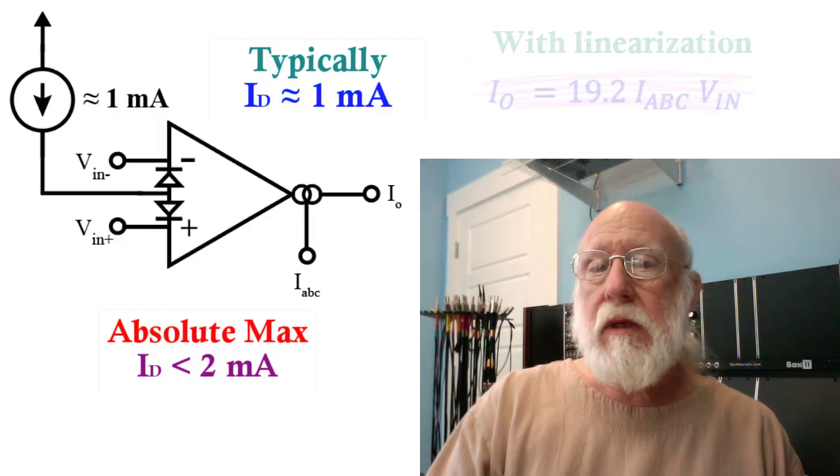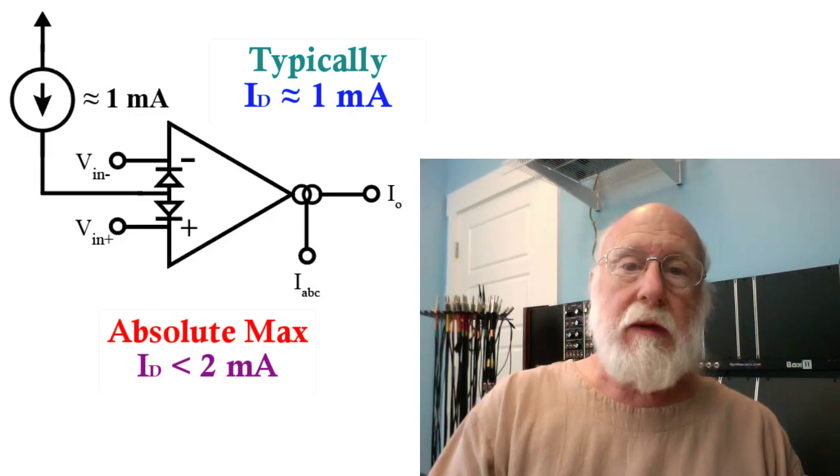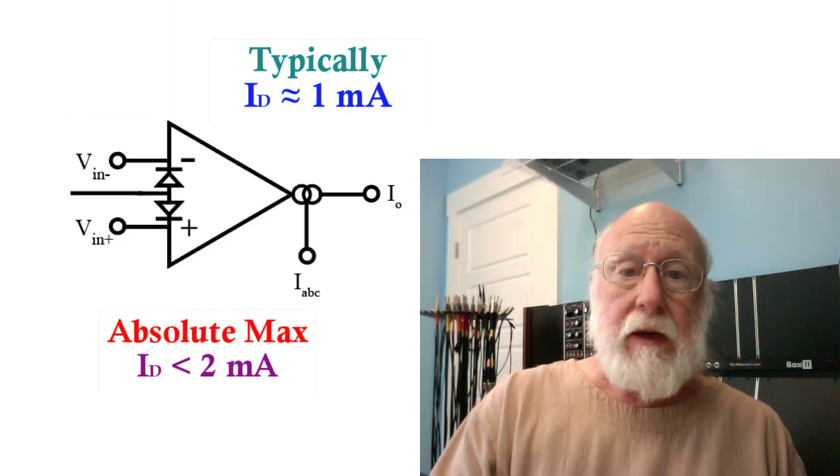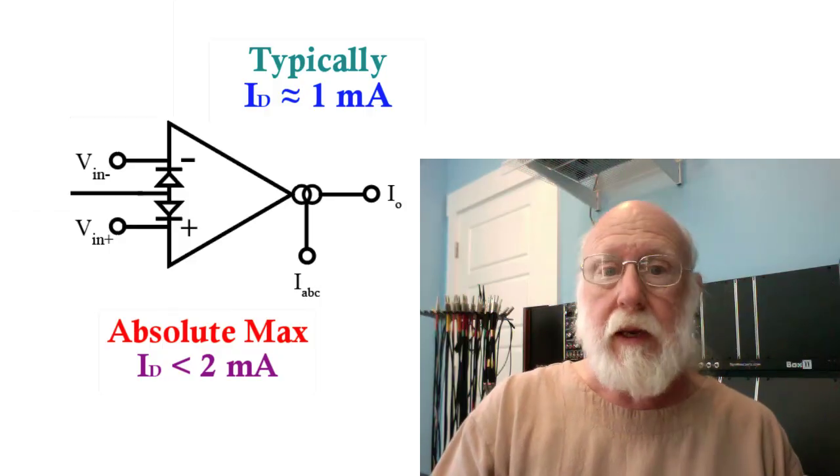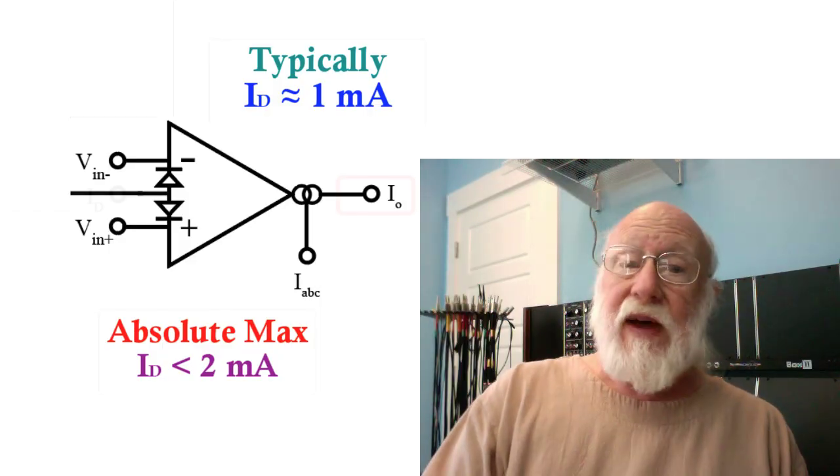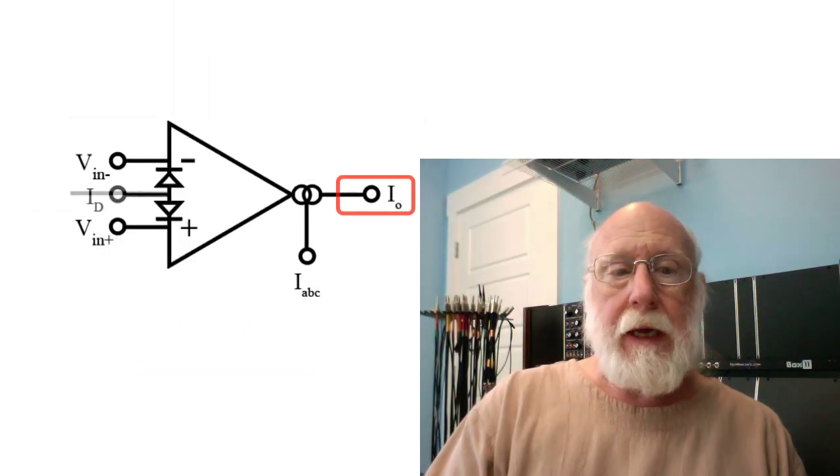If you're not using the linearizing diodes, you simply leave that input disconnected. Don't connect it to anything. Don't connect it to ground in particular. Just leave it open. Finally, the output current.